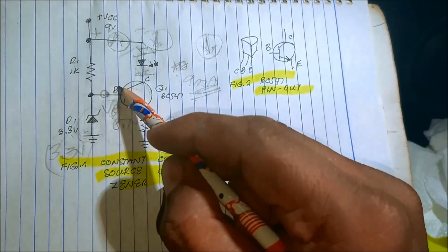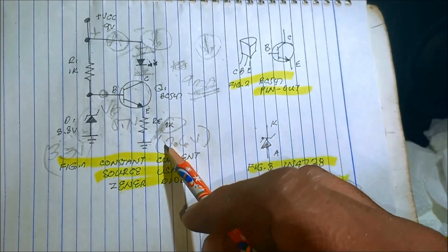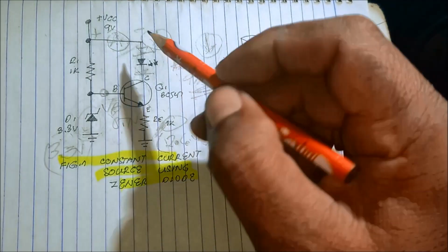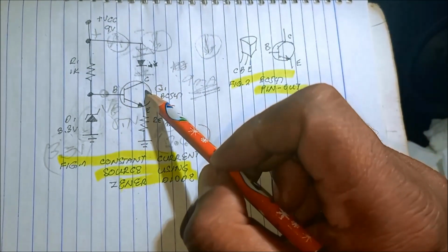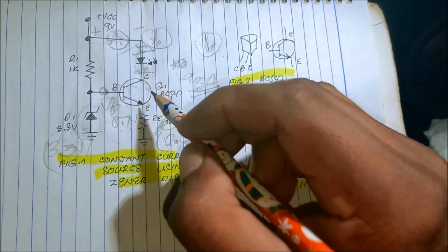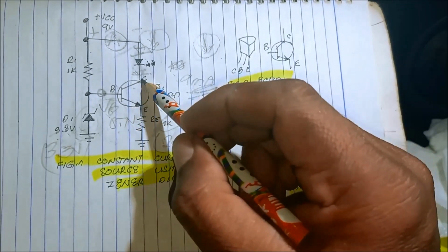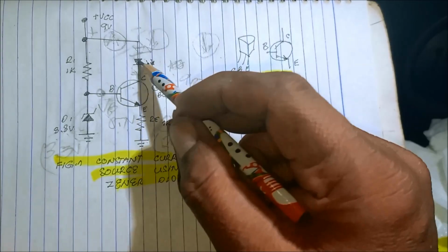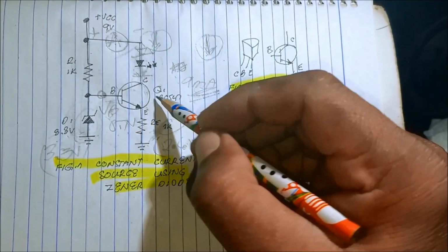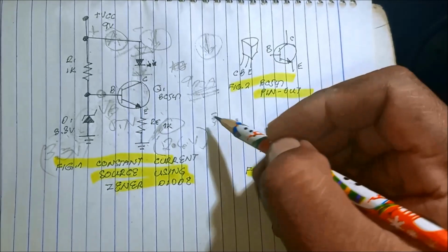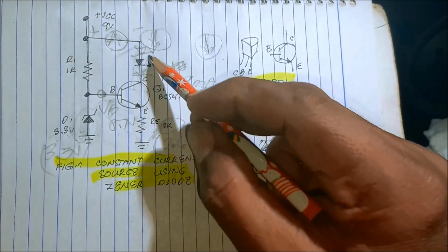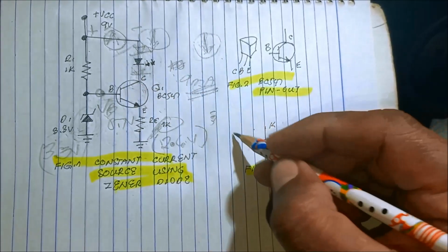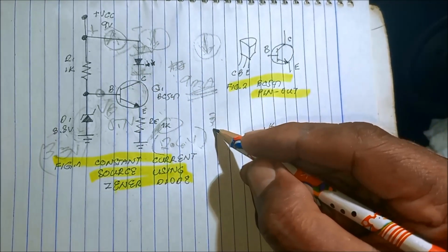Constant voltage at the base and voltage at the emitter, 2.6 volts. Here, this is the variable collector to emitter. When we connect one LED, it has a certain voltage of 3 volts, and when we connect another one, we now have 2 LEDs, with a certain voltage of, I think, 2 volts.